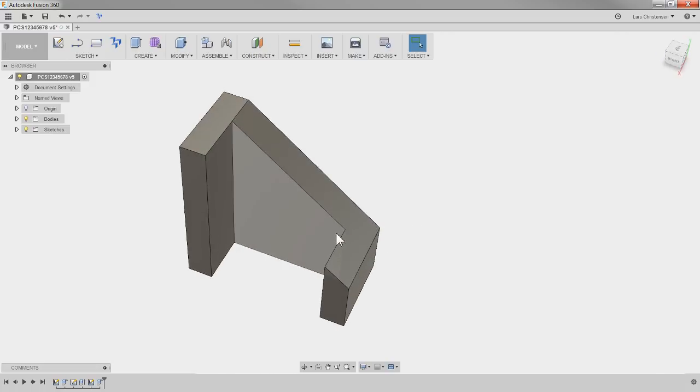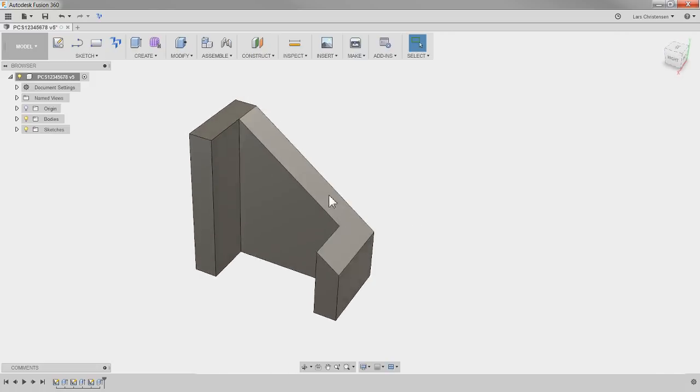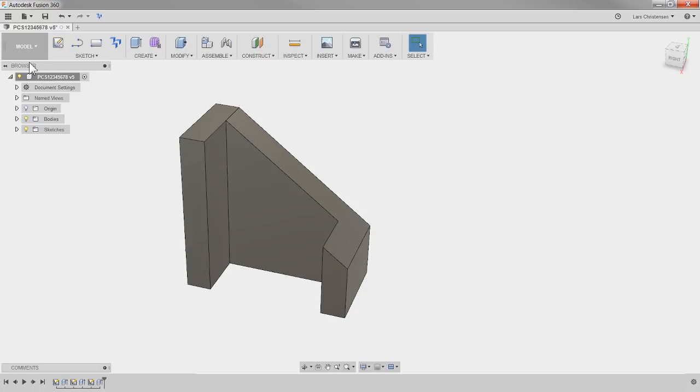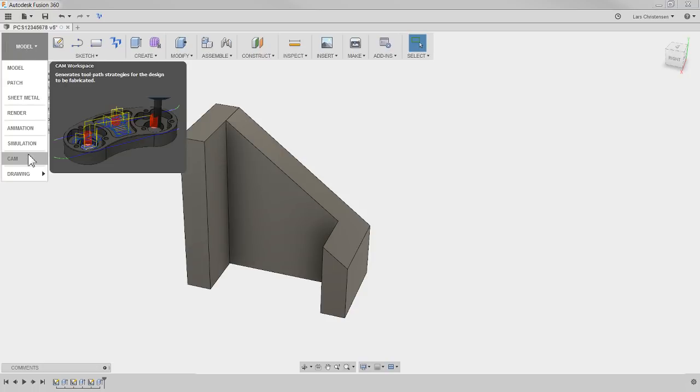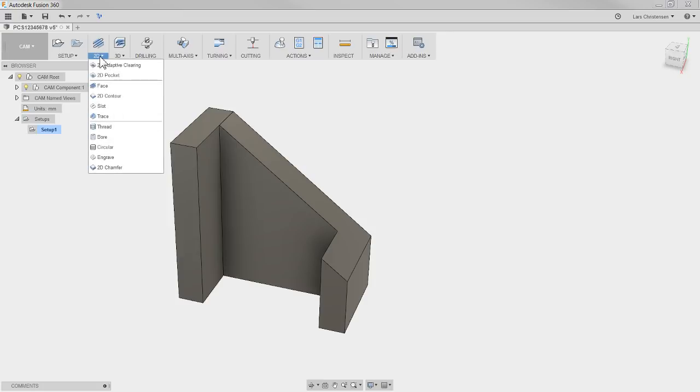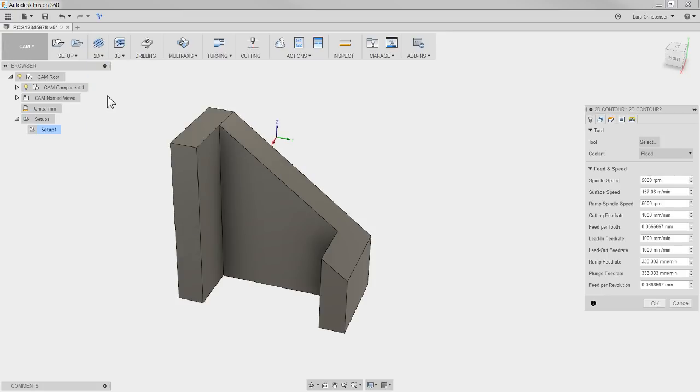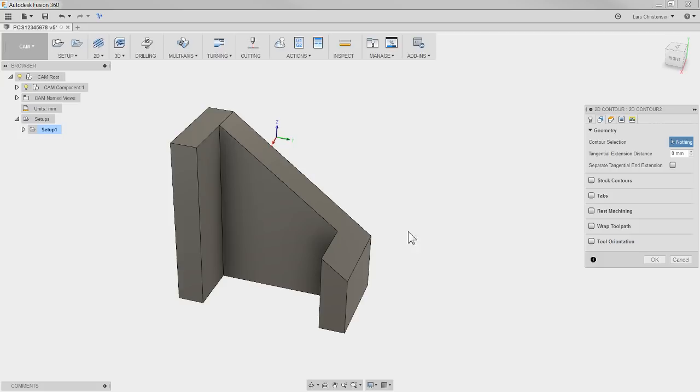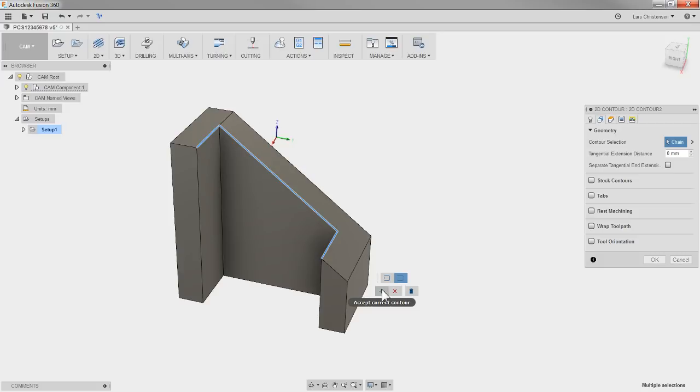See how we now have this angle thing, and you're thinking, how the heck am I gonna be selecting that in CAM? It works the same way. If I go back into CAM, select my contour, this works also for adaptive clearing and others. Select here, you will see how it selects the entire boundary. Well, if I reselect it again, I can select open contour, and I can literally select these 3 edges. Hit the green plus mark, and I have now added that little segment there.